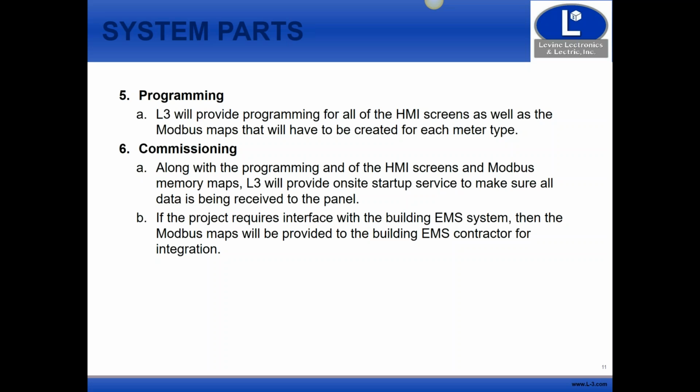If we're going to provide a quote for the equipment and the programming, then we're also going to provide the commissioning as part of that. So we're going to go on site and make sure that everything's up and running, that we're pulling data from every single meter into the monitoring system, that the data is available and being stored, and we can show somebody how to get it out if they need to.